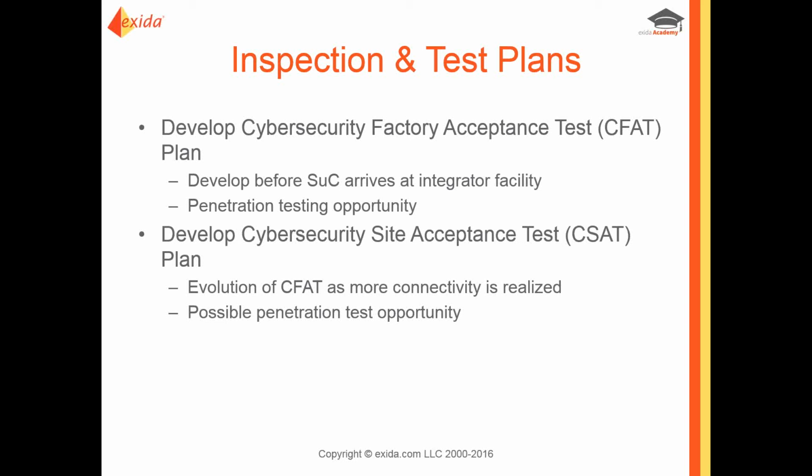The cyber factory acceptance test ideally is done as a portion of the factory acceptance test. It should be developed before the system under consideration arrives at the integrator facility. This is an opportunity to actually perform penetration testing, which is something you don't want to do when your plant is actually operating.